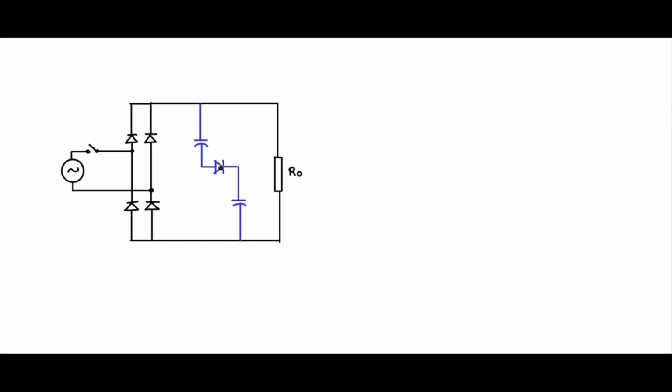There is a reason, we will see that. Charging is happening in this path. Half the charge will come into this capacitor, half the charge into this capacitor. So if you are having V0, each will take V0 by 2. Now when you want to discharge it, discharge each capacitor separately. So provide the discharge path.